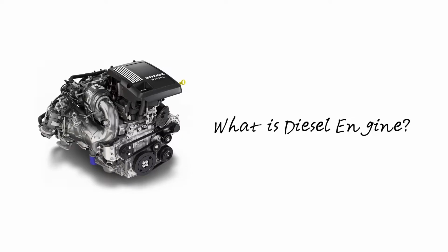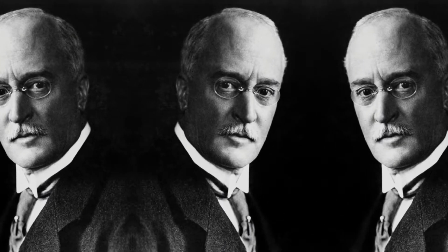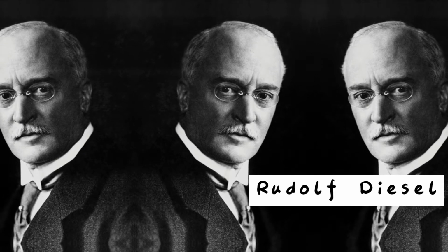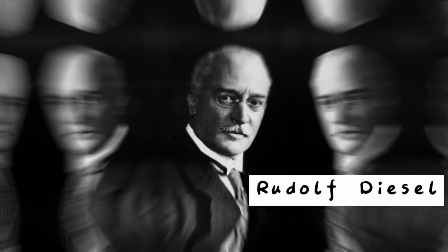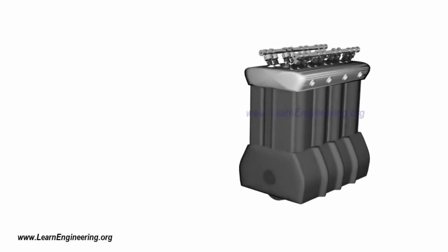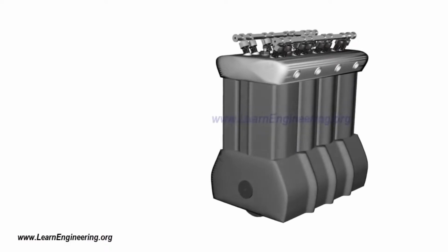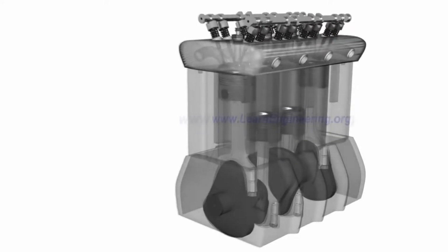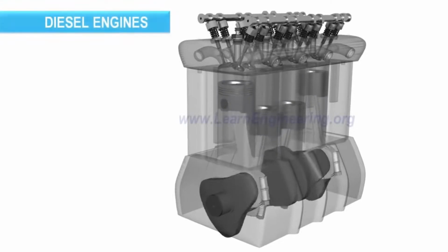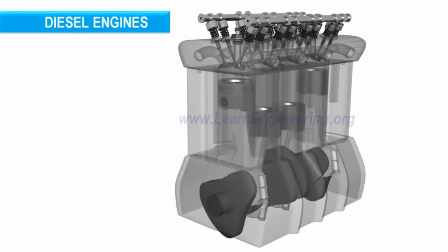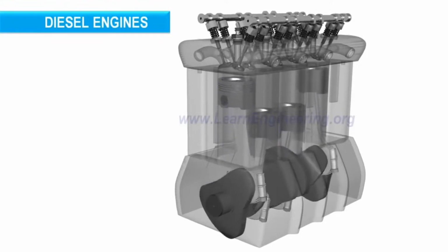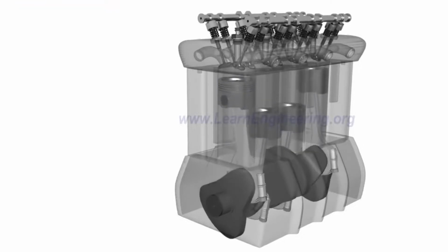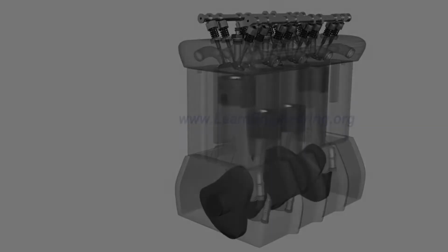The diesel engine was named after and invented by a German inventor and mechanical engineer called Rudolf Diesel. It is an internal combustion engine in which ignition of the fuel is caused by the elevated temperature of the air in the cylinder due to the mechanical compression. Thus, the diesel engine is a so-called compression ignition engine.